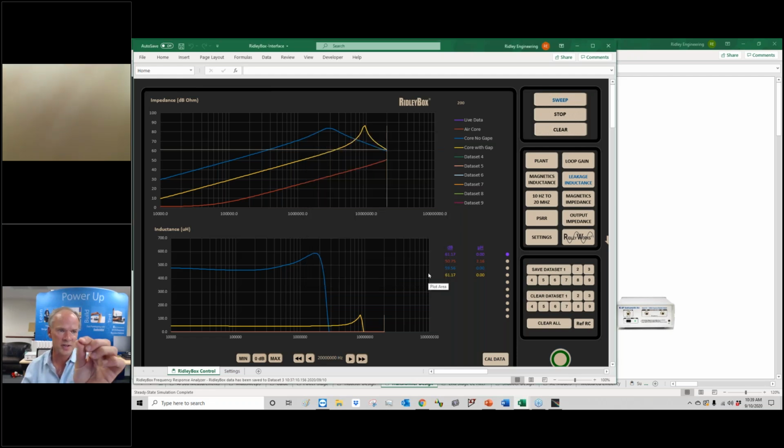I'm just going to hold a piece of resistor wire on the secondary. Normally you can't do that, but these are fairly high turns count. So the little bit of extra impedance of me placing it on there is not going to make a difference. If you've got a big step down turns ratio, you can't do that kind of thing. So let me place that on there.